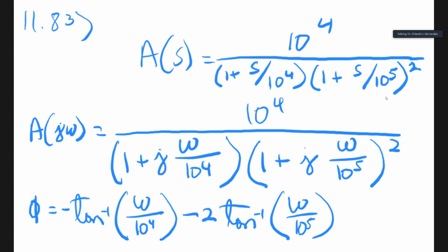Then they were asking us about the oscillations. Well, the first question is, when is the 180-degree phase shift going to happen? So all I have to do is equate this expression to 180 and find the omega 180.